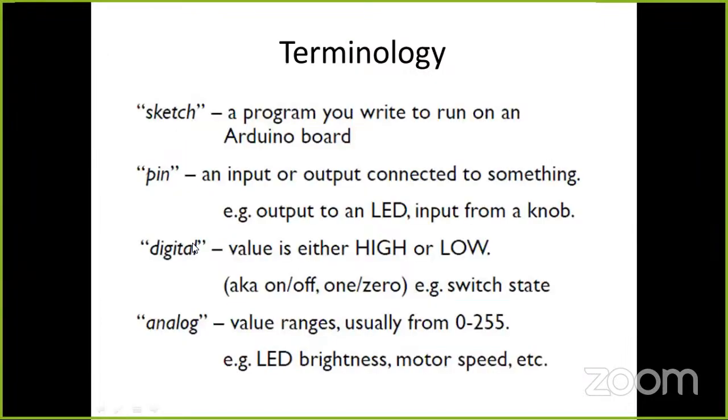So these are some terminologies, some keywords that we are going to use while programming. Sketch means the code that we are going to write in the Arduino board. Pin means input output pin, where we are going to connect sensors and actuators. Digital means we are going to write a signal either high or low, like turning the LED on and off. Analog means we are going to read a signal, like a temperature sensor value, that is analog read.